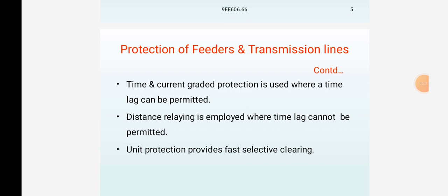For the purpose of protection, the bus bar zone includes the bus bars, the circuit breakers and isolating switches. When a fault occurs on a particular section of a bus bar or circuit, equipment connected to that section must be tripped out to isolate the section completely.